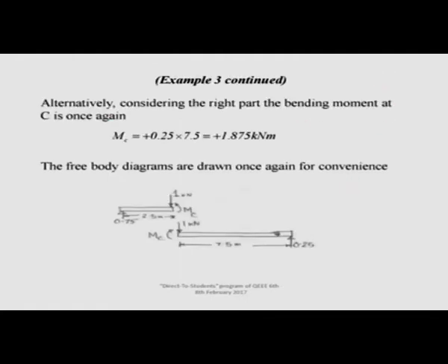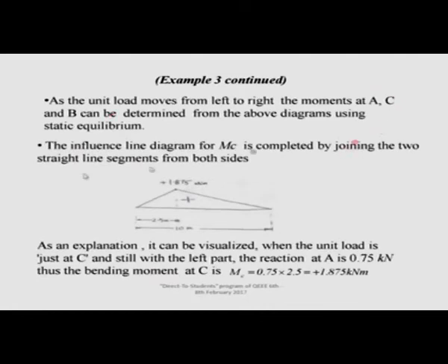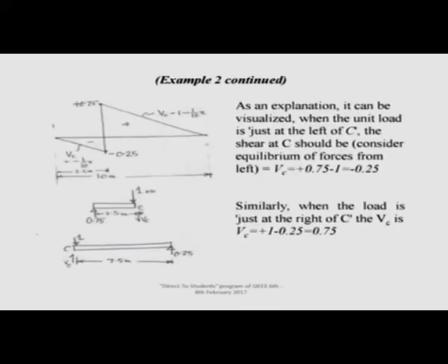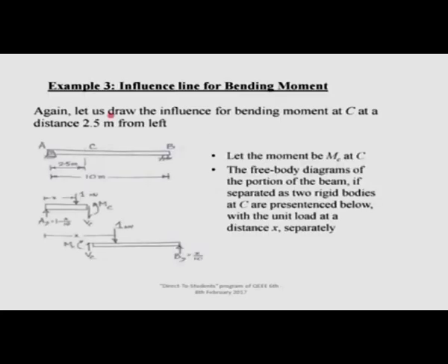Once again, since I have 1 or 2 minutes, I can just explain to you about the drawing of the shear force and bending moment diagrams, and the influence line for shear force and bending moment. See the bending moment, how we draw it here with the sign convention. Here is the shear force influence line, and here is the bending moment. You see here, there is a force here of 0.75 if the load is just here. So, it is 0.75, and then you have 1 here.